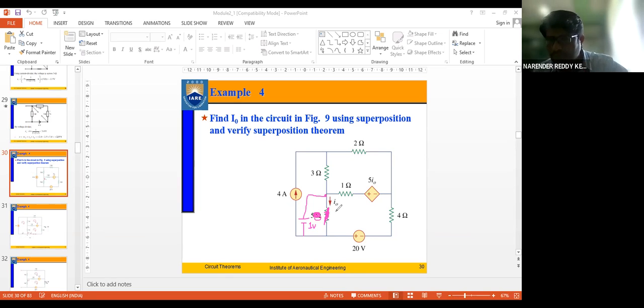So what is the need for having the VTH and RTH? What is VTH and RTH exactly? RTH is the equivalent resistance between these two terminals, right? If I connect a circuit like this on a breadboard, and connect an ohm meter here, I can get the value of RTH, isn't it? That's what we are going to get here. It has 4.8 ohms, isn't it? So what is VTH now?